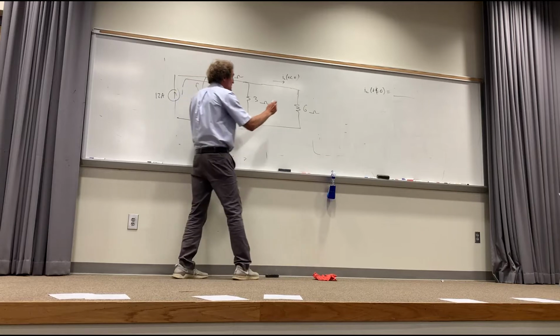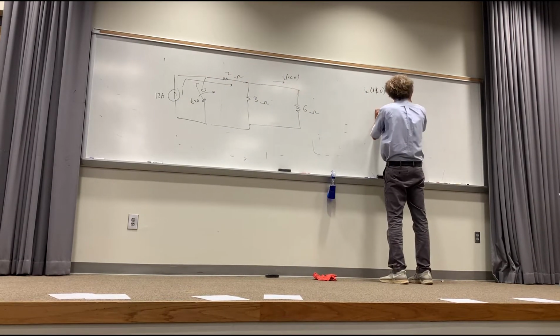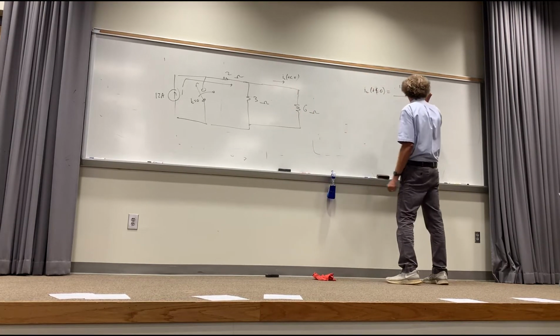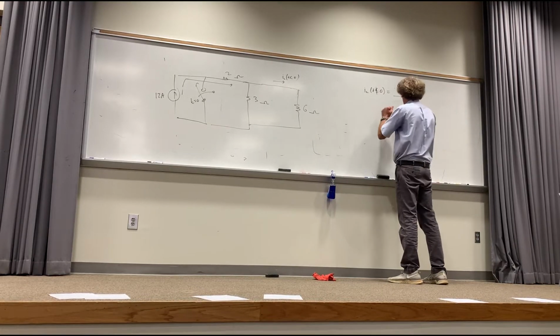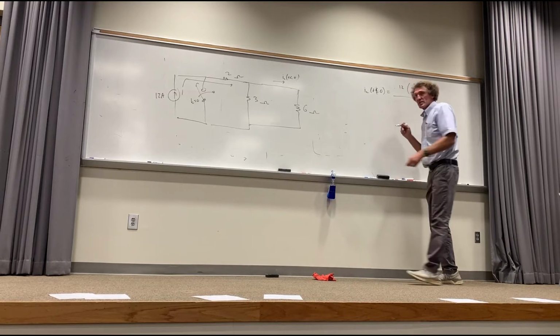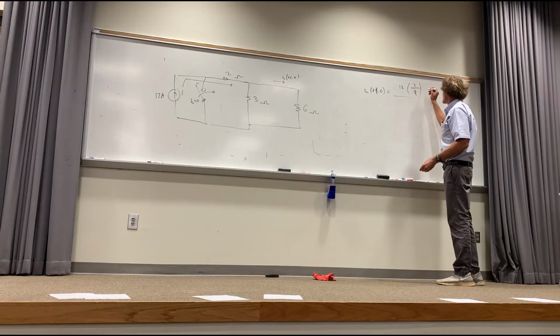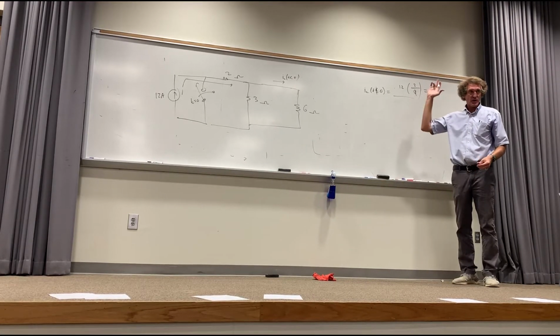How much flows this way? Well, that amount of current would be equal to the total current, 12, times the opposite resistance, 3, divided by the sum of the resistances, or 9. Can everybody see that, class? Or what would it be? 1/3 times 12, or 4 amps. Isn't that right? How many see this, right? Y'all see it, class? Give me a show of hands if you do. I want to make darn sure that you can see this. That's simple current division, right?